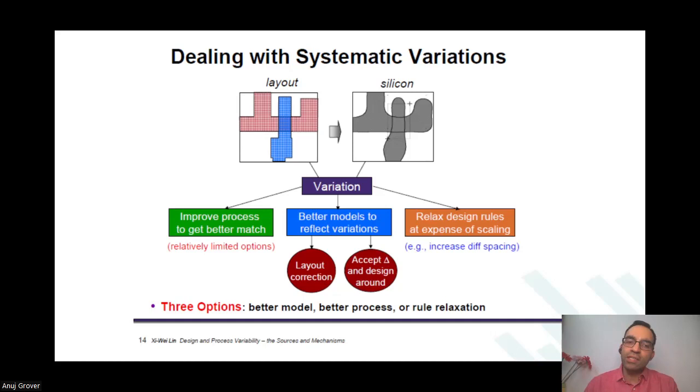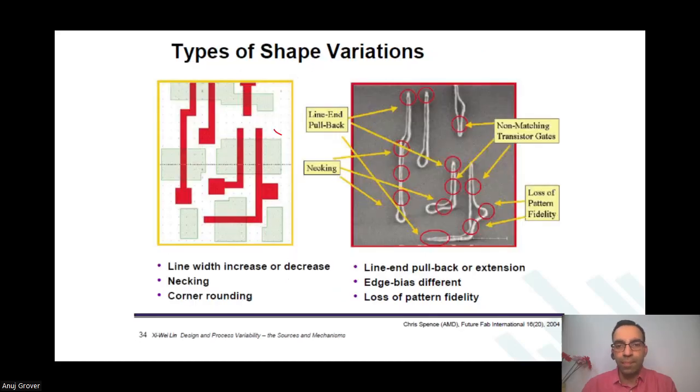You know what your process is, in the sense what resolution enhancement techniques you are using in your system. Since you are aware of those techniques, you can already make a simulator and find out that, okay, my gate region would actually be like this instead of this.